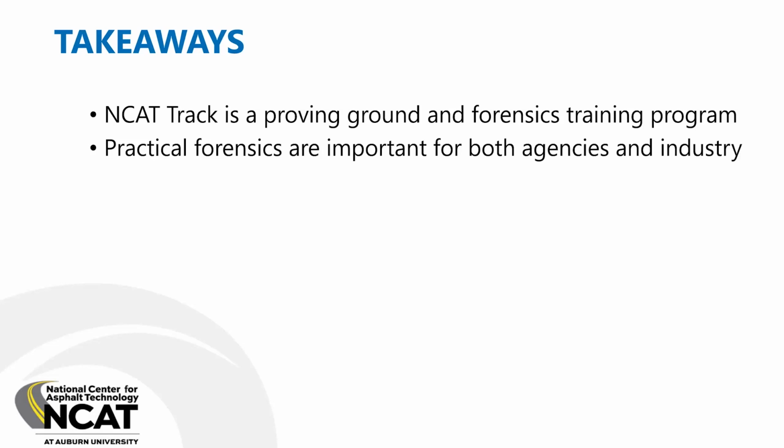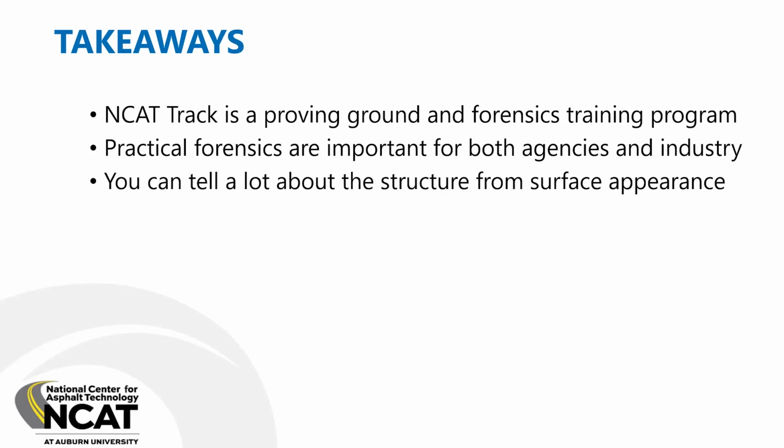If you want to bid a job and you're trying to figure out, hey, what are my patching quantities going to need to be? What are my repair quantities going to need to be? How thick is this pavement really? Not just the visual observations, but the dry augering methodology that Jason described. Very, very practical tool, and it's relatively non-destructive to do the dry augering as well.